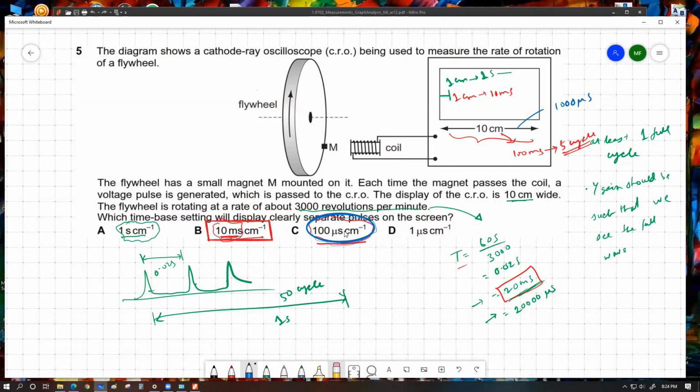microsecond, right? Yes sir. Now 1000 microsecond will not accommodate one full wave, because the time period of one wave is 20000 microsecond. So if we only represent exactly 1000 microseconds for the entire screen, we're only going to have a fraction of the cycle available over here.